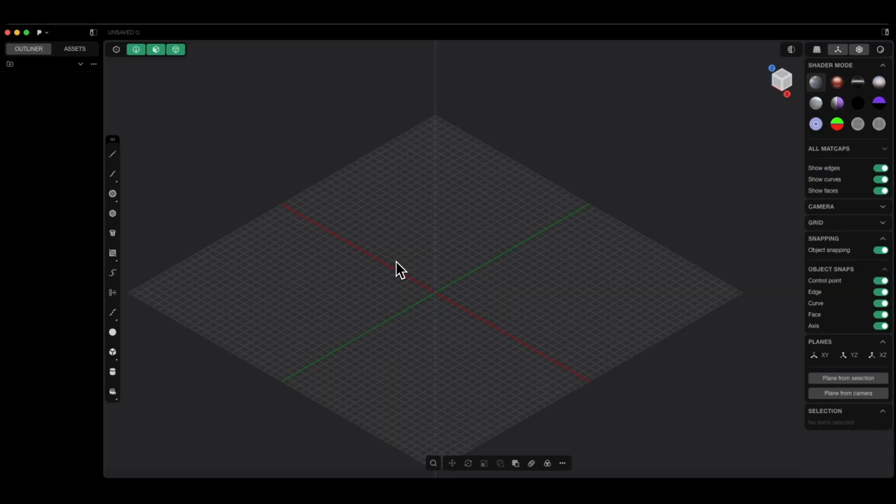When it comes to 3D modeling in Plasticity, we have an approach based on direct modeling here. It is not the typical 3D modeling known from popular 3D CAD systems, in which the 3D modeling approach is based on features and parameters. In the case of typical technical 3D CAD systems, we model parts using features and parameters, and the 3D modeling is based on an operation history. In the case of Plasticity, we don't have parameters and we don't have an operation history.